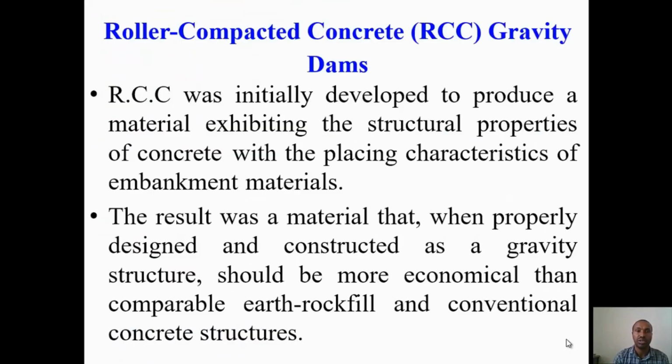Okay, now let us proceed to the roller compacted concrete gravity dam. I think RCC, most of the time, is economical compared to a conventional gravity dam. RCC was initially developed to produce a material exhibiting the structural properties of concrete with the placing characteristics of embankment material. So the construction procedure is the same as an embankment: just spreading, then compaction.